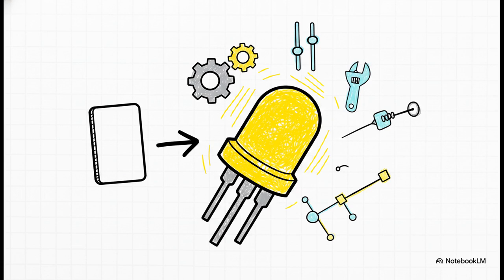By tweaking underlying parameters like saturation current, you can build a totally custom component. Need a specific yellow LED with exactly a 1.938 volt drop? You got it. You can even save it into your library for future projects. That level of flexibility, it's just unmatched.